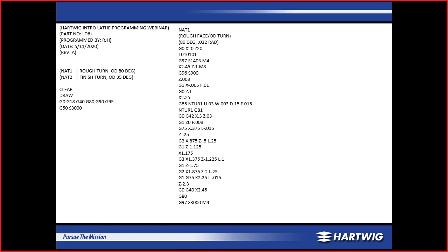We change the spindle RPM back to G97. I like to do this before I rapid the turret back to the limit, because if it stays in constant cutting speed, the machine will slow the spindle down to a point where it's almost at a complete stop, which can be really hard on the brake over time and can also cost you cycle time. So we'll go back to G97, and the S3000 is going to be the RPM my finishing tool will start constant cutting speed at, so that I don't have spindle ramp time in between.